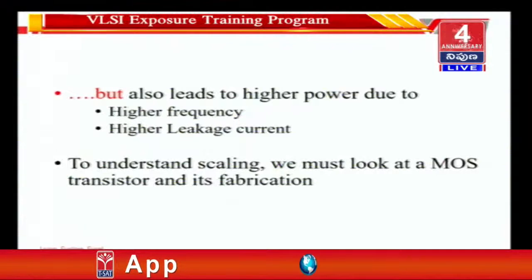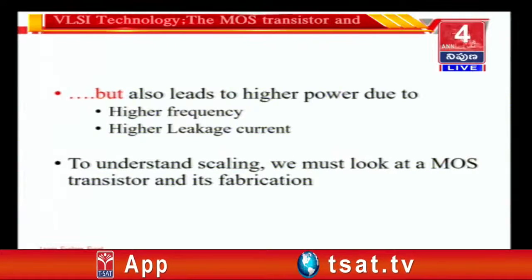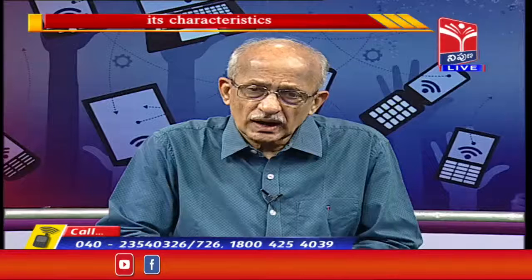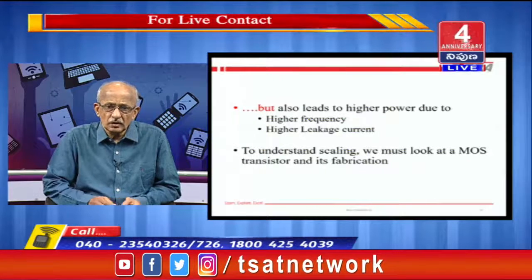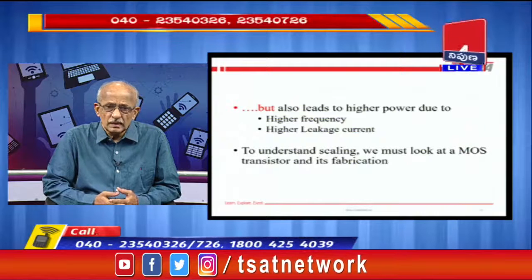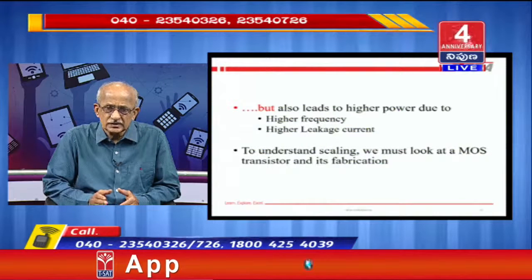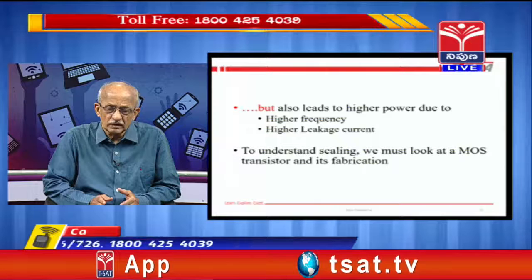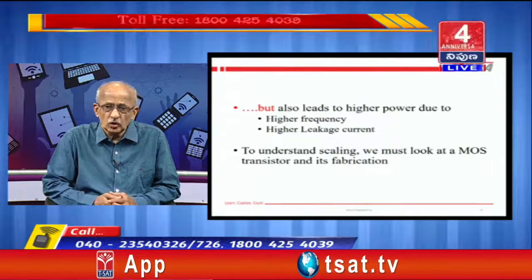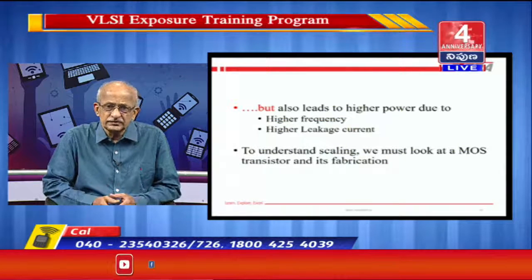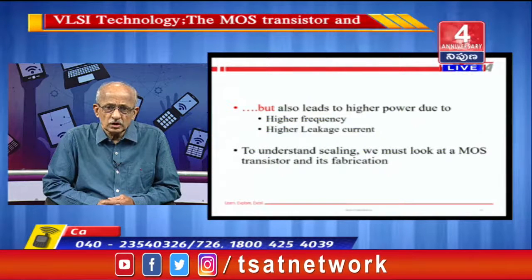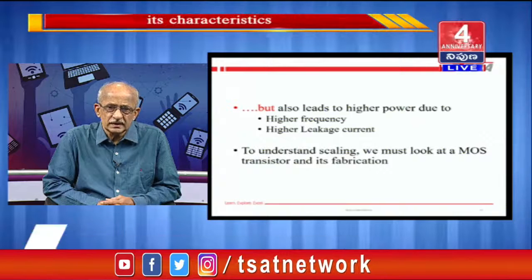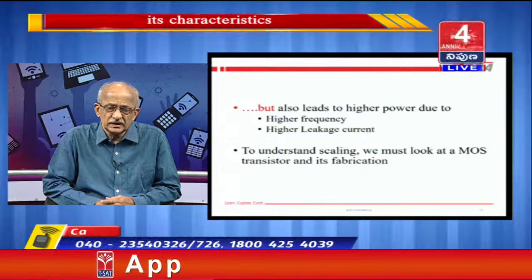What are the disadvantages of shrinking? Of course, it leads to higher power. When you shrink, you add more devices, and therefore you work at a higher frequency, and therefore the power also tends to increase. Although individual transistors may have smaller dynamic power, the leakage power is more. Overall it tends to increase the power. Therefore, these days there is a lot of work going on towards making power decrease in VLSI circuits.